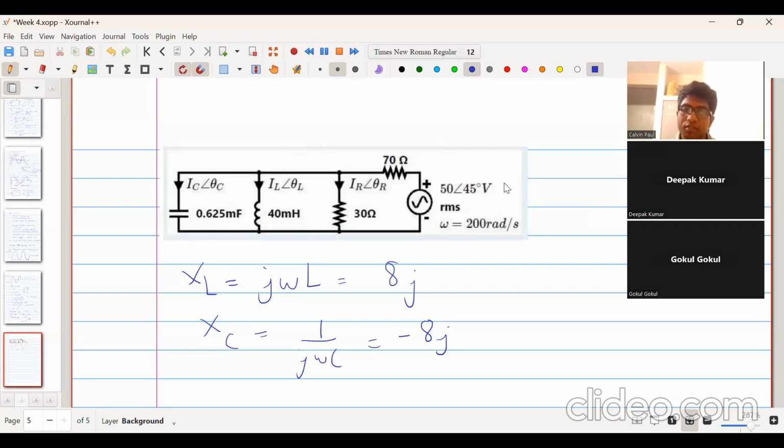Oh, okay. So now, see, phasor analysis is applicable when there's a single frequency. And here there's a single frequency, so we can apply phasor analysis. Phasor analysis is for the steady state behavior of this system. You're right that there is resonance occurring, and we will solve the circuit considering resonance to happen.